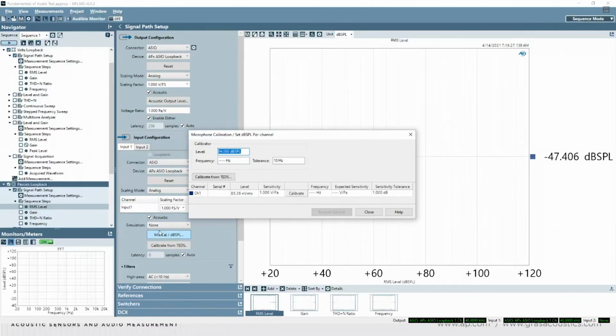Instead, we are always using some type of transducer, a device that converts from one domain to another. We call it a microphone, but the input to the microphone is sound pressure level, and the output is an electrical signal. In our analyzers, in some location, there is a place for us to enter the ratio, or what we commonly call the sensitivity of our transducer, which will tell us the conversion from pascals of sound pressure to volts, so we can then express it in our software and look at measurements in the domain of pascals. But really, the analyzer itself is measuring volts.